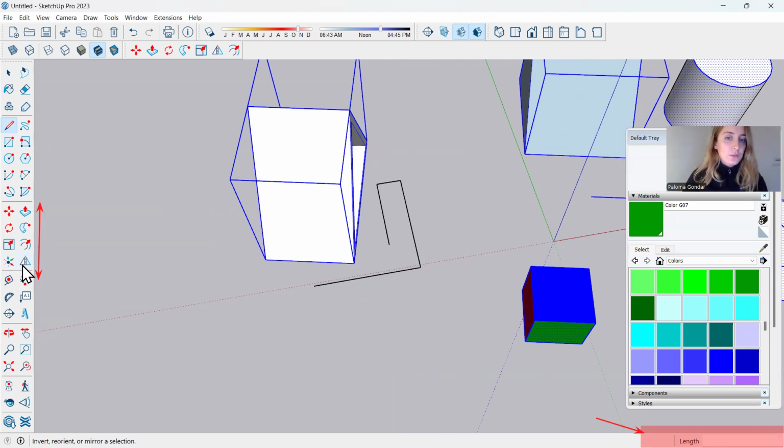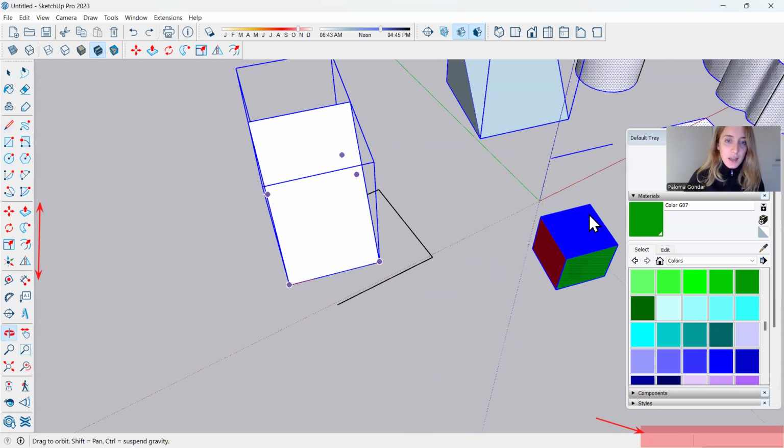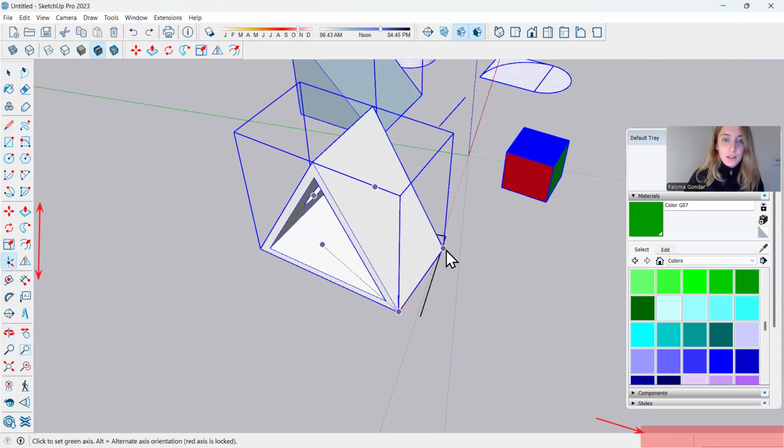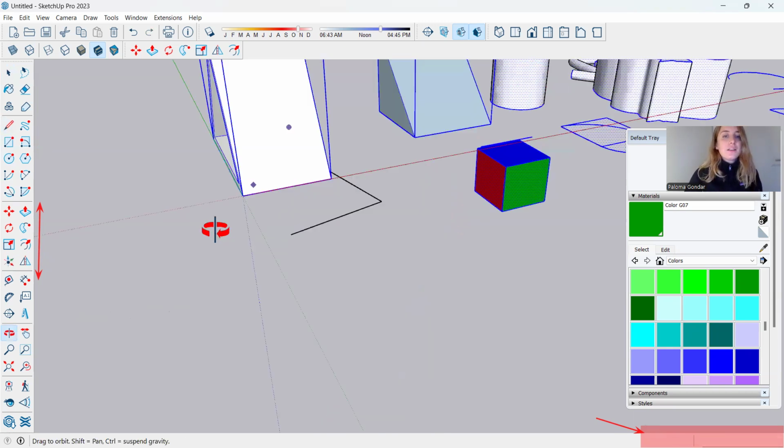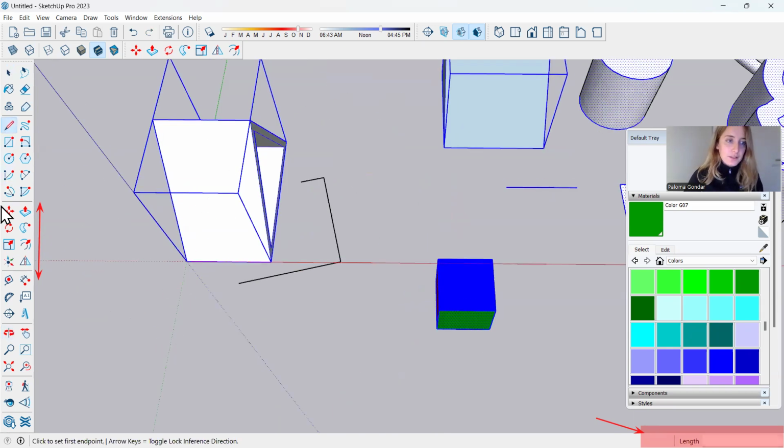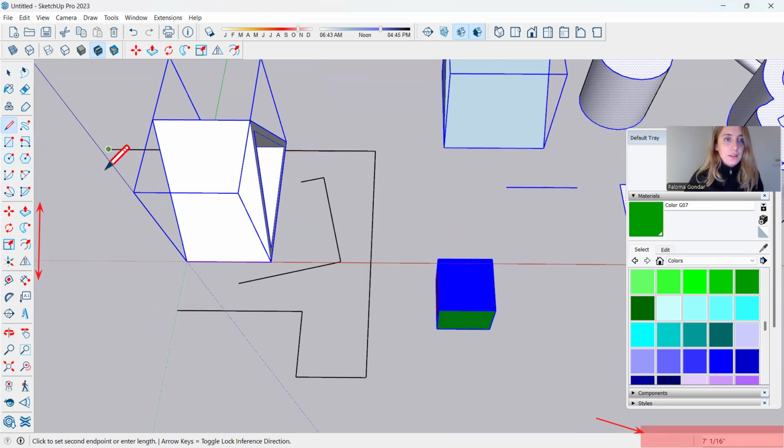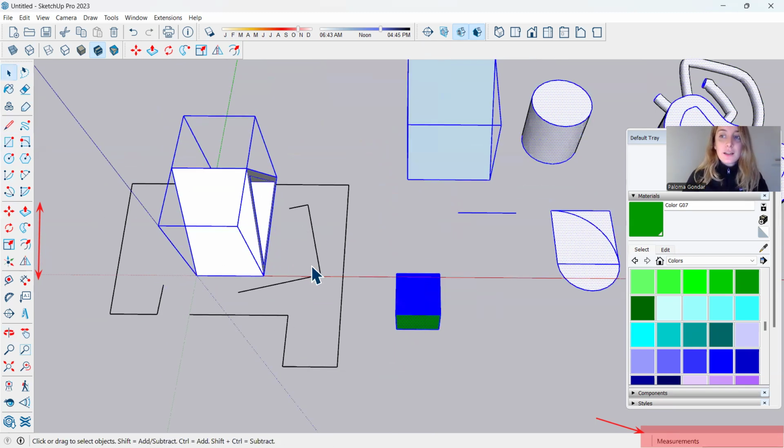So in this case, what we can do is change axis. So I select axis, one click in this axis. Second click, we are setting up the green and the red axis. So second click, and then the third one, we set up where we want the third axis, like the green axis here. And I set up these axes as the new axis. How do I notice that? Because now if I do like this, now it's aligned and stuck to my new angle, so I can keep drawing without any trouble. So for example, I want to rotate again to the last axis, that is this one.